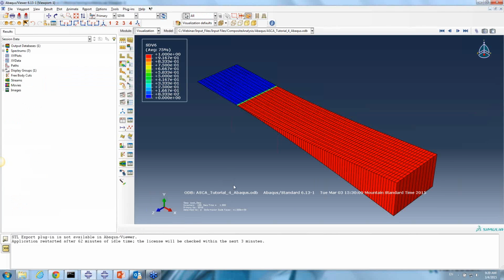And this gives us the opportunity to see a few things. We'll go back to SDV1, and you'll see a 0 to 26 scale. 0 means there's no damage that's occurred. This SDV1 is indicative of the current damage state of the element, and it is tracked from 0 to 26. We also have SDV2, which is important, and this tracks the progression of the element as